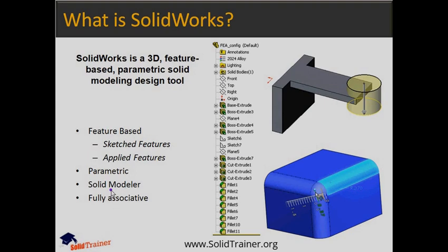A solid model is the most complete type of geometric model used in CAD systems. It contains all the wireframe and surface geometry necessary to fully describe the edges and faces of the model. In addition to the geometric information, it has the information called topology, which relates the geometry together. A SolidWorks model is fully associative to the drawings and assemblies that reference it. Changes to the model are automatically reflected in the associated drawings and assemblies. Likewise, you can make changes in the context of the drawing or assembly and know that those changes will be reflected back in the model.